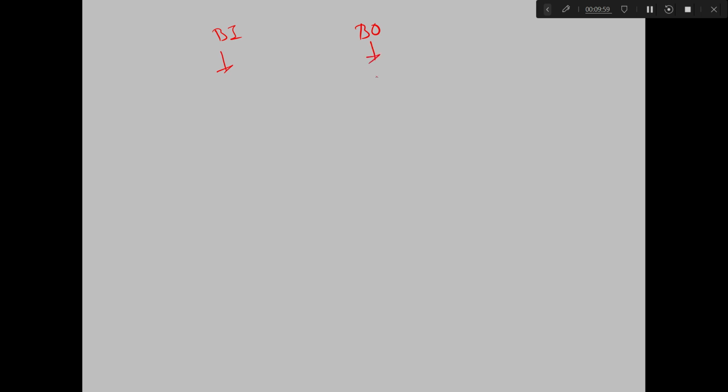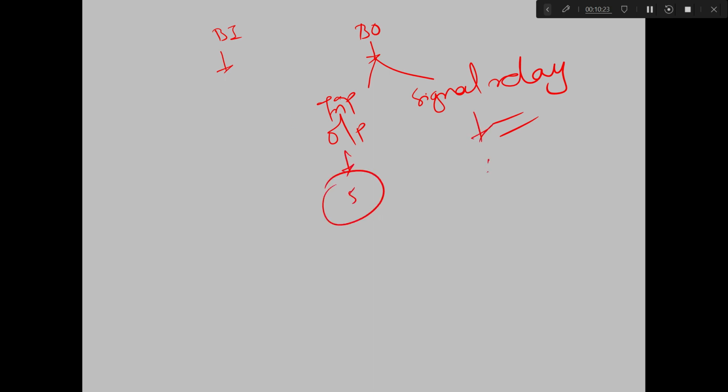There are two types of output in this: trip output and signal relay. You have to see as per your scheme which is assigned to which, and I will consider our scheme that is already over here. There are basically 5 trip outputs, that is trip relays, and one signal relay. So there are 6 output relays, and I will discuss the configuration of all these 6.